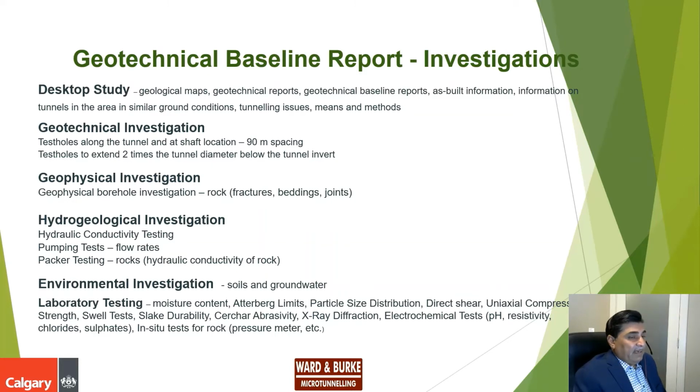And after that, we have to do laboratory testing, and those are specific to projects. But in Calgary, for tunneling projects that I have done, we have done these type of tests: moisture content, Atterberg limits, particle size distribution, and that is for soils. Atterberg limits we also do for claystone. Direct shear for soils and bedrock.